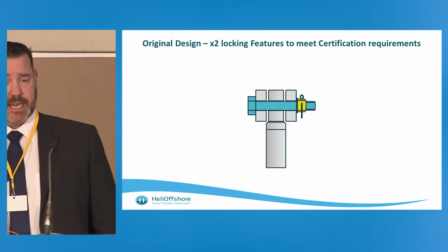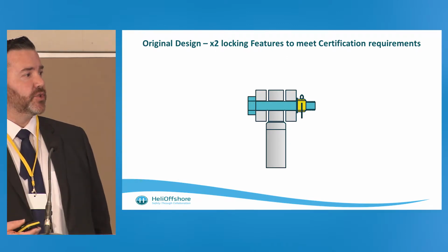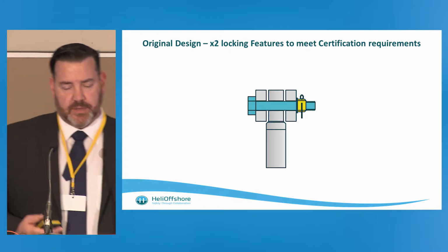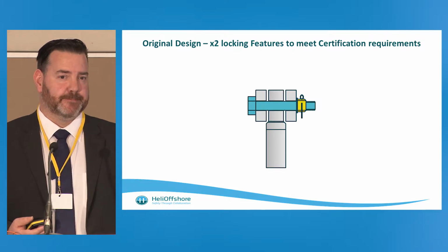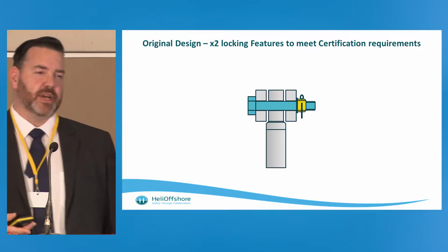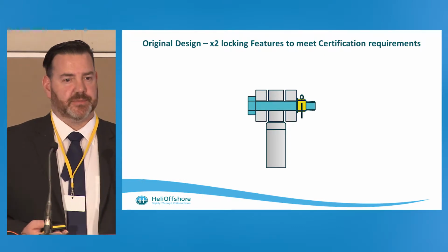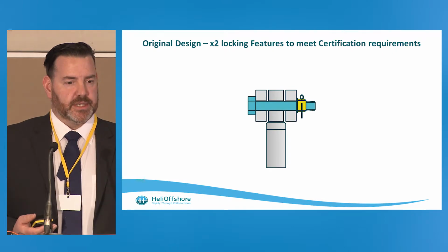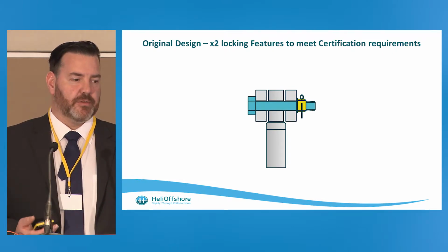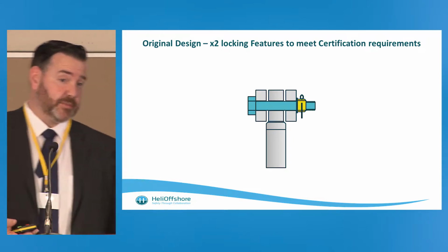So it's just an eye end, a fork end, a bolt, a washer, stiff nut, and a split pin. And there were 3 of these installed on the aircraft. When the investigators were going through the wreckage, they discovered that that bolt was missing. And not only was the bolt missing, there was no evidence on the remaining parts that the bolt had fractured in service. So the only conclusion the investigation report could come to was that the engineers somehow forgot to fit a stiff nut and forgot to fit a split pin.